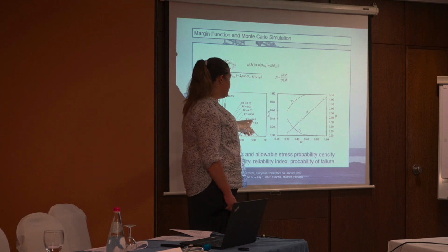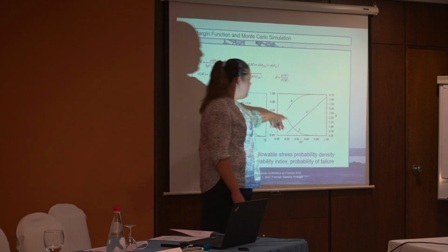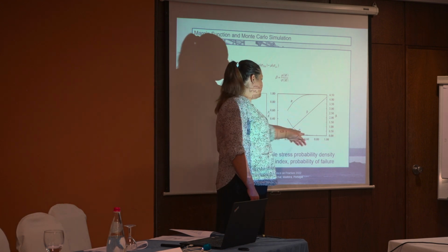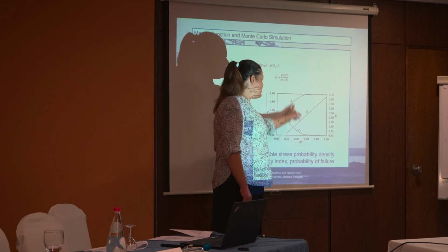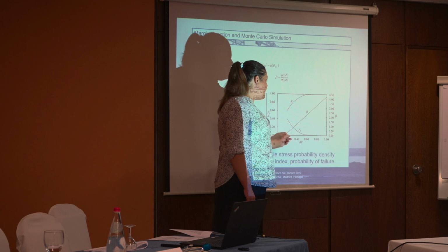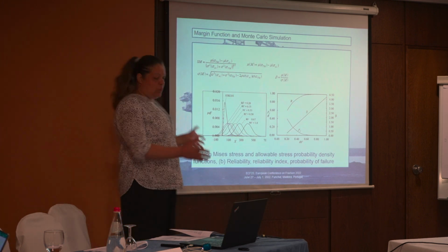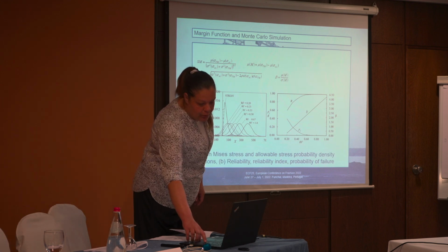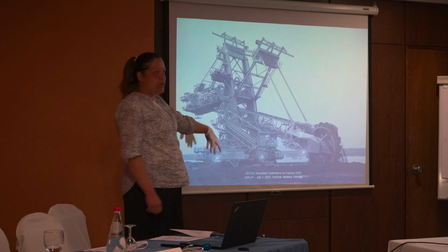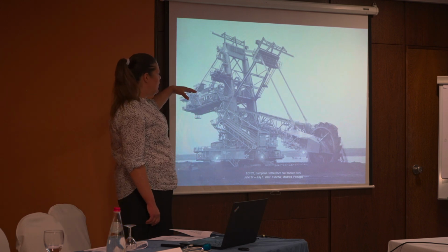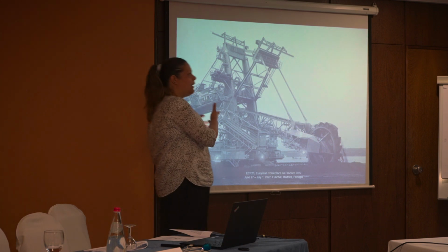But when you have 0.67, your probability of failure would increase. When you get there, it would increase, and the reliability would decrease, and beta would get smaller. So, once again, I was talking about pure structural reliability of this construction based on stress distribution, and we are planning to introduce even more loading cases in this analysis.